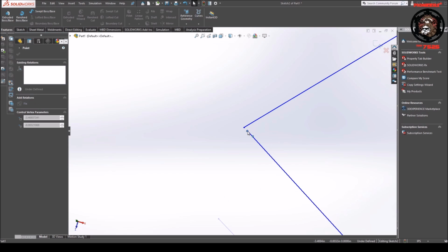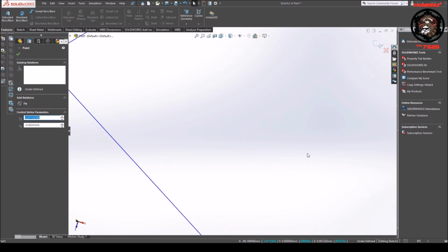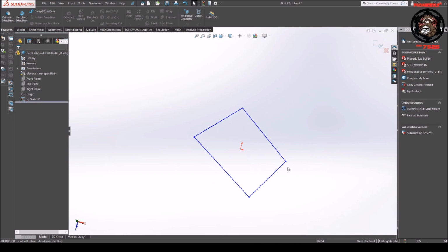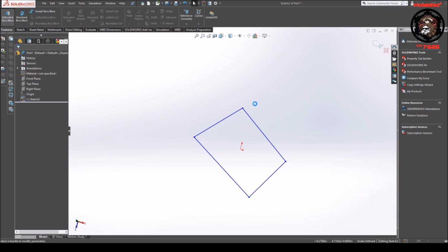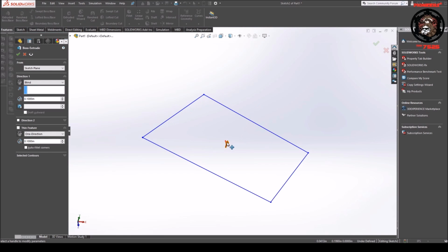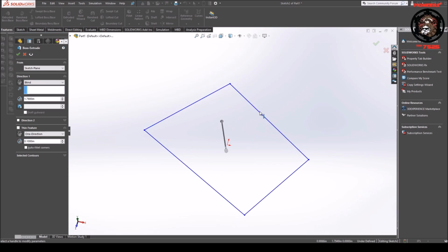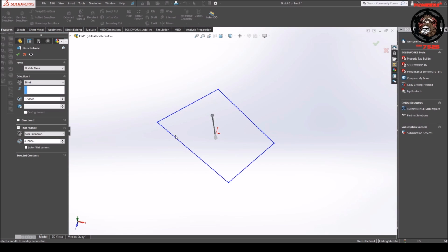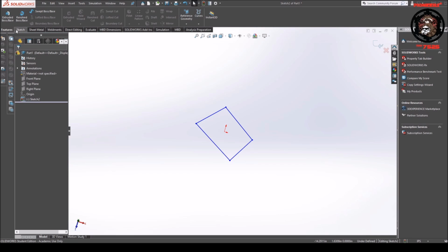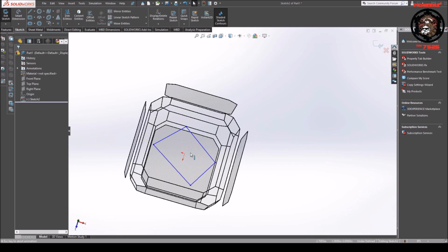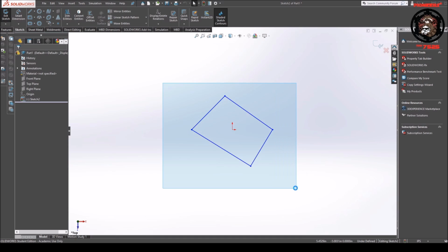Right about here, you would think it's enclosed. However, when you look at the sketch, it doesn't shade inside, so that means it's not enclosed. And when I try to extrude, it gives me an error. It won't create the solid part. So these are neat features to look into. I think initially it's not enabled, so you should probably click this. It'll be to your own benefit.